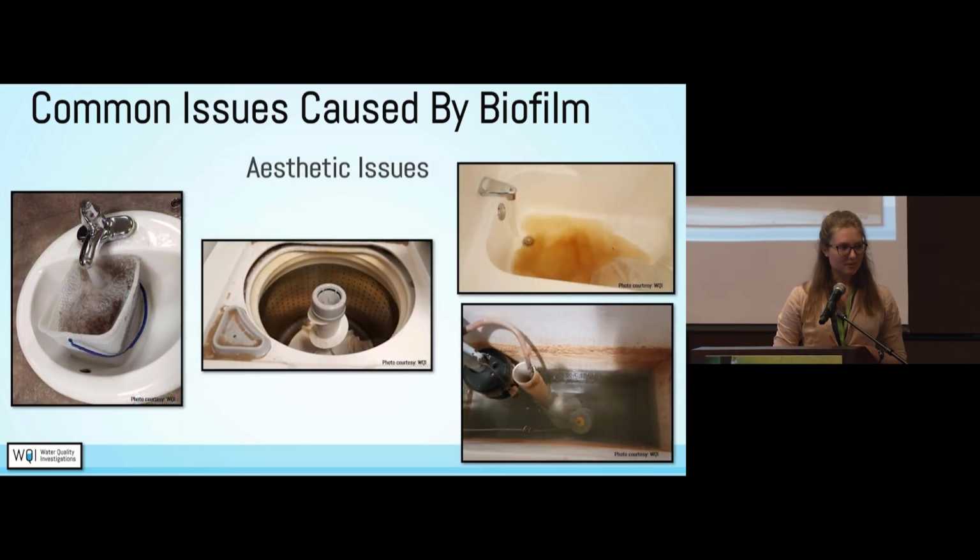A lot of you are probably familiar with aesthetic issues that happen: discolored water, people have odor and taste issues. One thing that is easy that we like to do when we go into a residence, we'll often pull the cover off their toilet tank and look at that, because I will admit I don't clean my toilet tank. And so that is an area where water is going to sit and it's not regularly cleaned. It gives you an instance of, am I smelling a sulfur smell? Am I smelling something else? Is the water here red or brown or something like that?